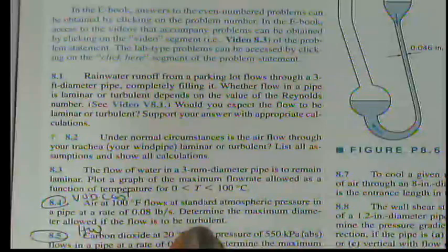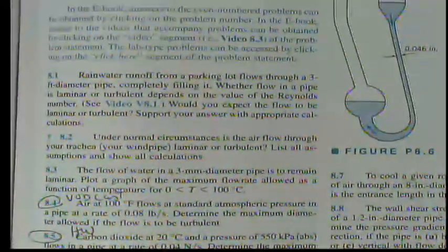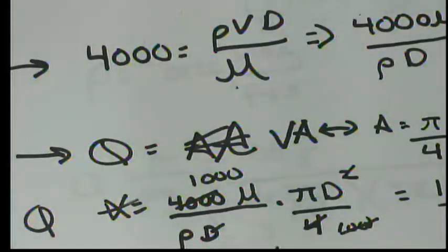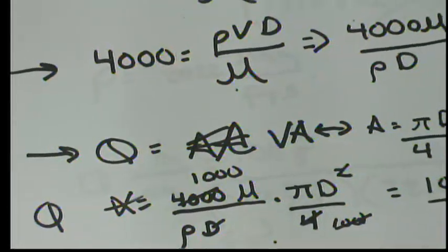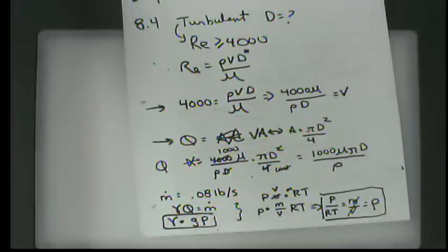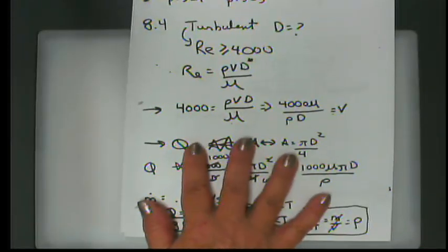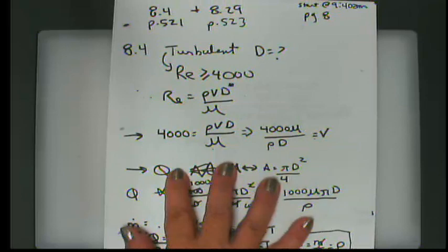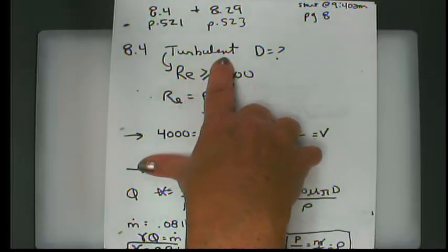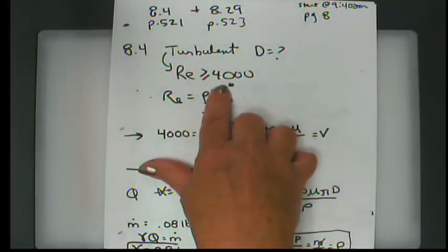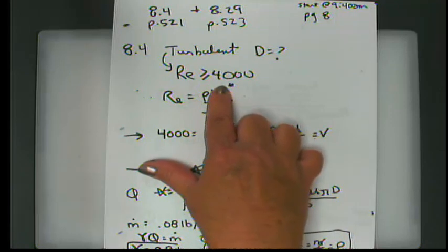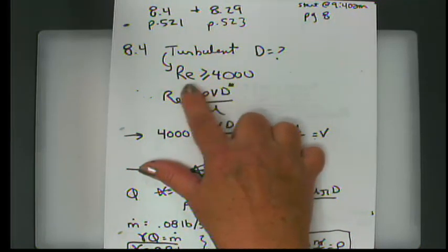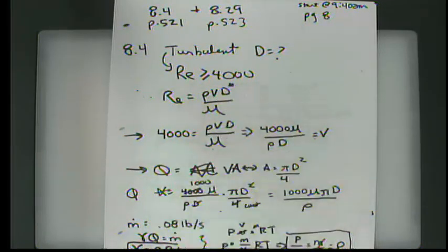Okay, what's it really saying? Well, what it's saying is that if you have a small diameter, the fluid will move faster and the motion will be turbulent. If you increase the diameter, the velocity will slow down and you will have a more laminar flow. So they want us to at least have whatever diameter is going to be required to keep this in the turbulent flow range, which I've said, if we don't have better information, can be considered that we have a Reynolds number of greater than 4,000.